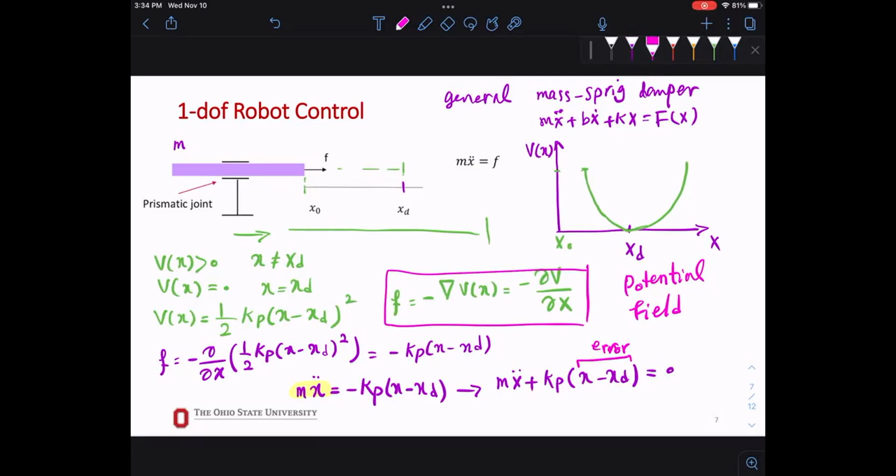What does this remind you of from the PID control? This is the P control, right? The P part of it. So this is the controller. We created this from the behavioral system, and these two together now look like a mass on a fixed spring, right? So you see the difference. Then just write out your PID controller. But we need to understand how our system behaves, then we can design our controller for it.